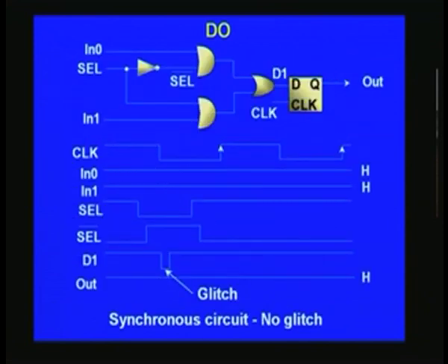And another thing we talked of earlier is the glitch, which is an unwanted, uninvited guest that you would like to eliminate. So for example, this circuit gives a glitch as far as this combinational circuit is concerned, and a narrow pulse like this is known as a glitch. How it is produced, we will just have a look. These are all plain AND gates here with an inverter here, and then finally these two are ORed here, and then applied to a D flip flop.